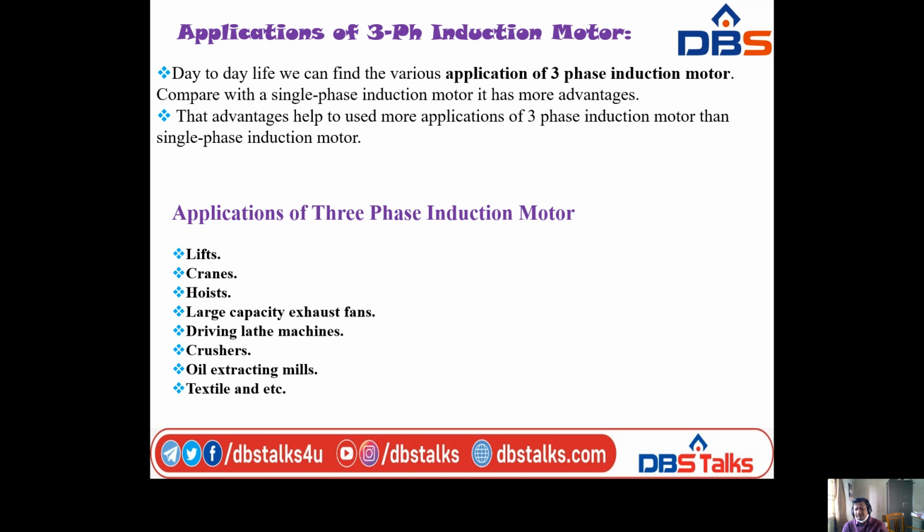Lifts. First of all, a lift requires high starting torque at the start. That means the starting torque is high. In that situation, we utilize a three-phase induction motor, especially the slip ring induction motor, where starting torque is high. Lift, crane, hoist: these three require high starting torque. So a high starting torque three-phase induction motor is nothing but the slip ring type of induction motor.